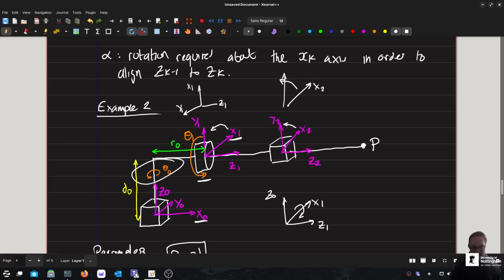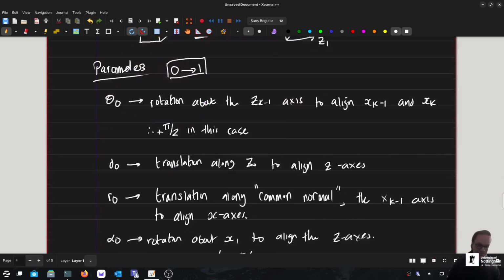Again, for this theta 0 term, we don't care because we are always going to assume, from the respect of the prismatic joint, that when we're doing our kinematics the rotary joint hasn't moved. And any rotation that the rotary joint does not affect the 0 frame at all. 0 frame is just directly connected to it, then this is just rotating about it. But because frame 2 is connected to frame 1, if one rotates, the other must rotate as well. I hope that clarifies it.